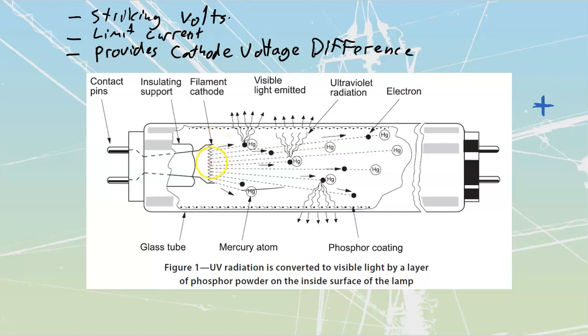Everybody's seen this. You know that a light bulb, an incandescent, well, maybe you don't know at this point, but it used to be everybody knew that if a light bulb was going to burn out, an incandescent was always when you turned the switch on. It would all of a sudden go real bright, poof, and that was it. Because it was that thermal expansion it could not handle. We're not supposed to be flipping these things on and off for the same reason.